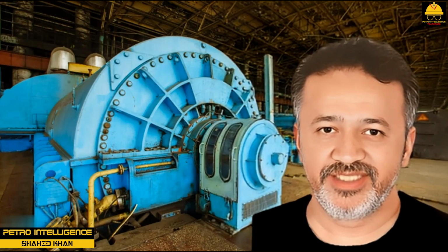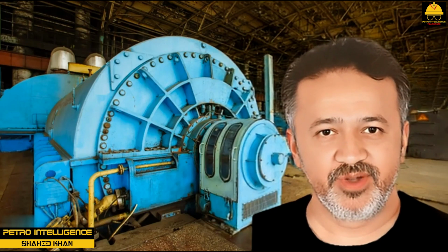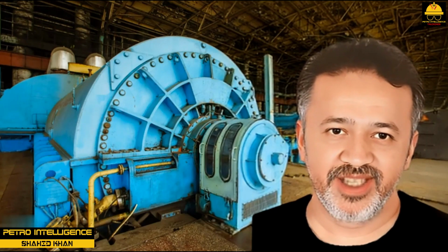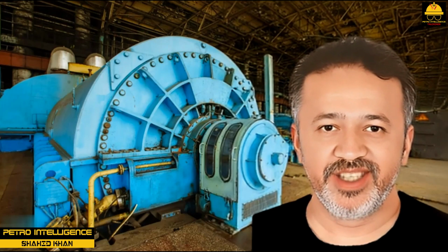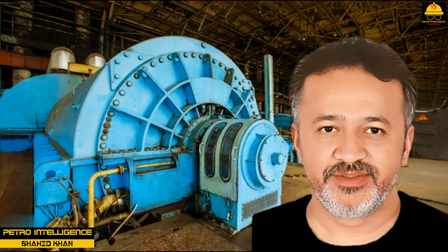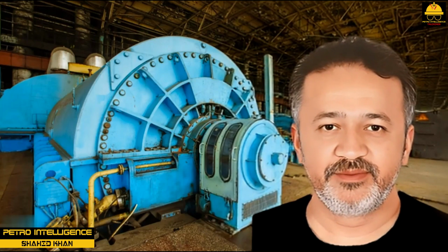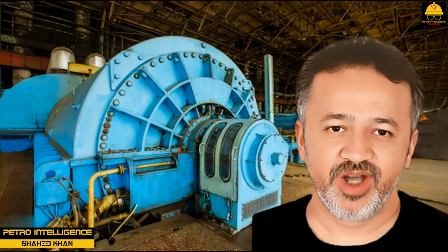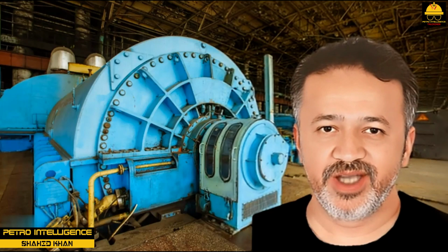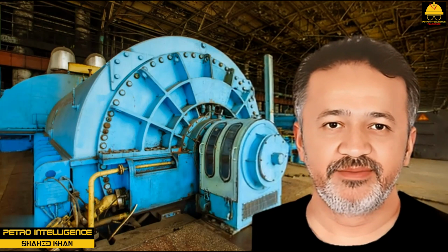As steam enters a steam turbine, it is directed into a nozzle. The nozzle directs the steam onto the blading, which is attached to the shaft. The blading and shaft make up the rotor. Movement occurs as the steam strikes the rotor, converting the steam energy into mechanical energy.